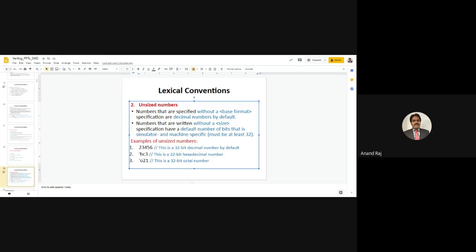Now see here, we have learned this thing. I'm assigning output as 3'b000. We just learned this convention in this class. Just go through this program, guys. You'll find a lot of interesting things here. I've used the case statement here: case, endcase, endmodule. If anything else comes, default. It is XXX, don't care. So just go through this program, write this program, take a pen and paper, note down this program, or try to analyze this program by yourself. Okay.